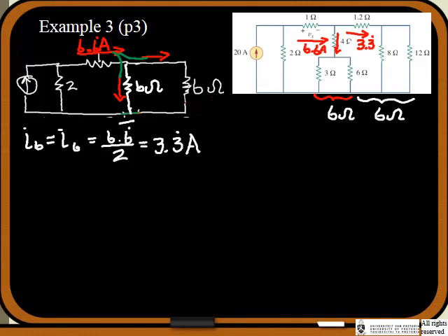So now I've got a choice. We can do a current division again to figure out I8. Let's call that one I8, and this one is I12, and then use I squared R. So let's do that approach first, and then we'll do the voltage approach.